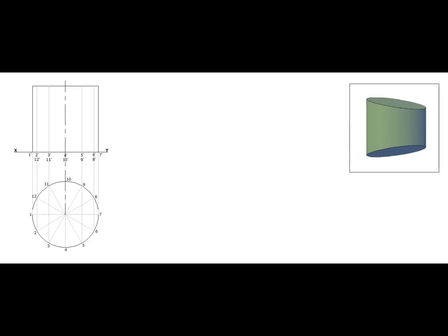There are two cutting planes. One is passing through the bottom end of left-hand side. The other one is through the top end of left-hand side. Further, the cutting plane passes through the right-hand side, with an in-between distance of 30 mm.